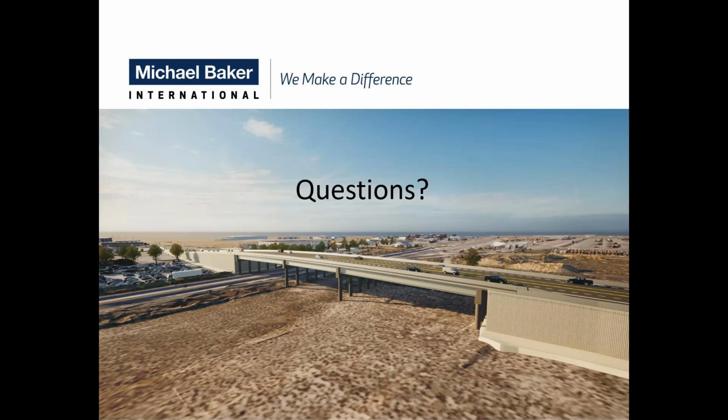So the columns were, well, longitudinally they were essentially pinned, but the columns were fixed at the top. When we modeled the footing contribution, the differential deflection, the actual column deflection, was less than with the fixed column, when it was fixed at the base. And so the deflections were close to our limit, but which was good.